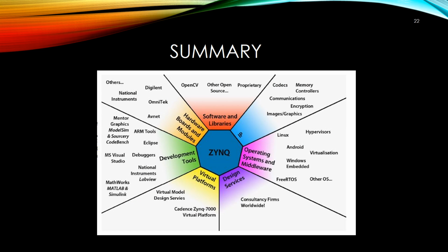This presentation has reviewed the general architecture of the Zynq device and detailed its two component parts, the PS and the PL, together with the resources for interfacing between them. The processing system was shown to include a dual-core ARM Cortex-A9 processor with associated extensions for SIMD and floating point processing grouped together in an APU unit along with memory resources. The capabilities of the APU and its interfacing to the rest of the processing system were highlighted. The internal structure of the PS as a whole and its connection with the programmable logic was also explained.